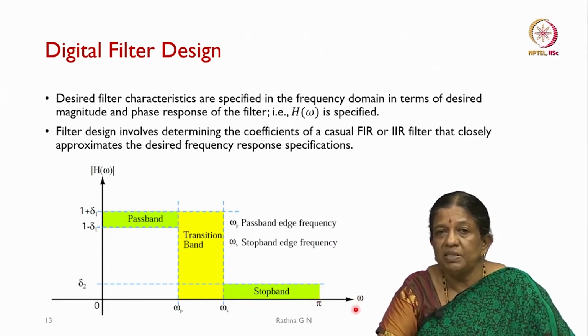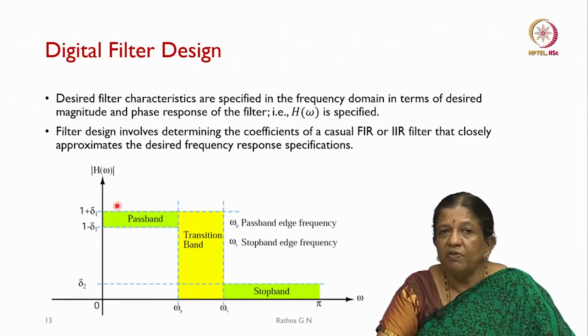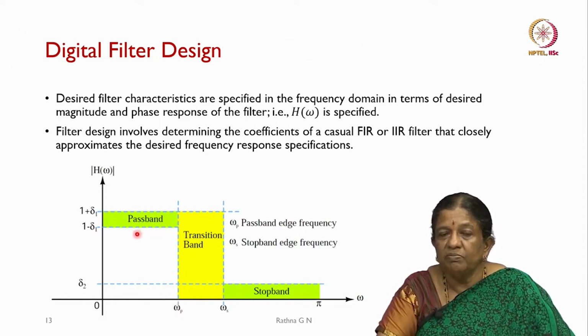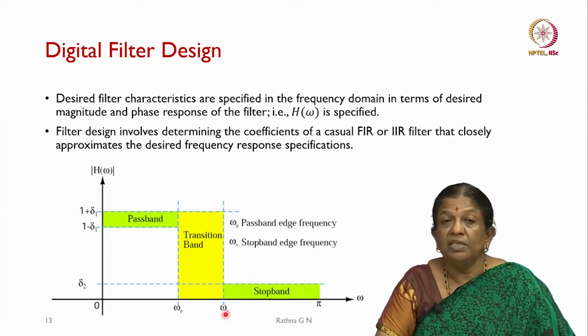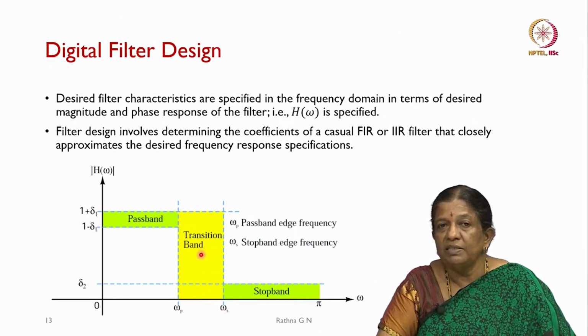So, the highest frequency is represented with 2 pi, hence we can consider the frequencies that are present only up to pi. And then we say omega is the pass band frequency, that is from 0 to WP, if the example is taken as a low pass filter. So, I want to allow all the frequencies which are in the pass band, that is WP, where I want to stop collecting my frequency components. Then I am going to say stop band. WS is where I have to stop my collection of components. The difference between WS and WP, we call the transition band.